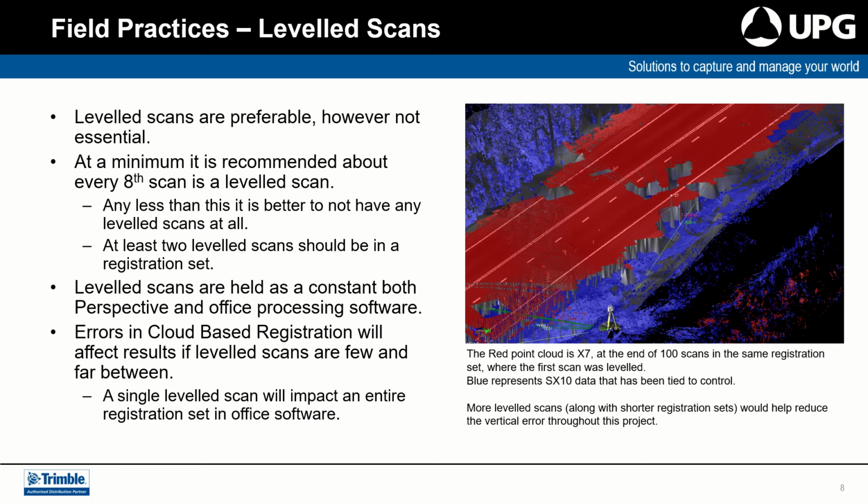Leveled scans are preferable, however not essential. Leveled scans generally take a little bit longer. While only minute, they can take a little bit longer than an unleveled scan. At a minimum, it's recommended about every 8th scan is a leveled scan to ensure that you're returning to some form of level and that any errors aren't being shifted all the way through the scan data.